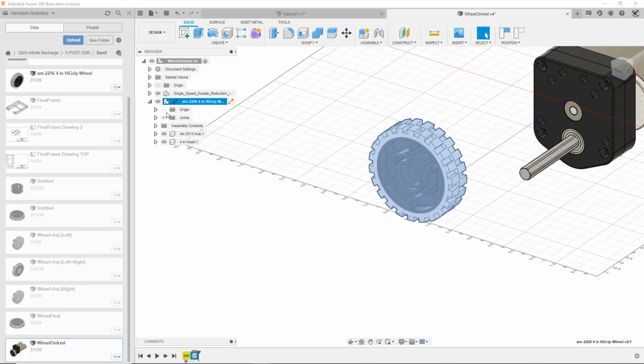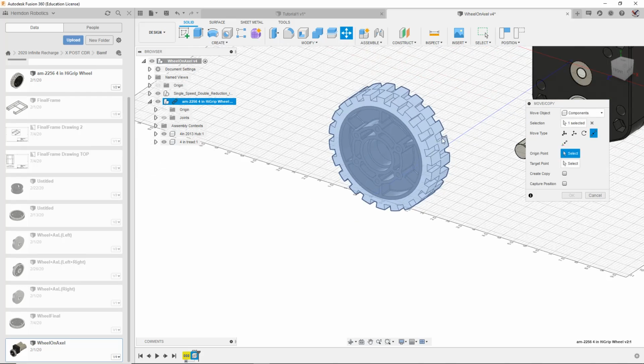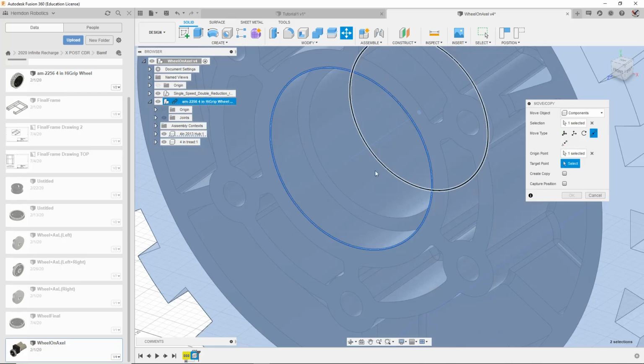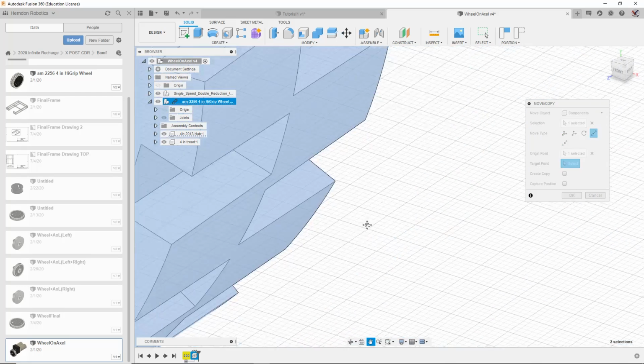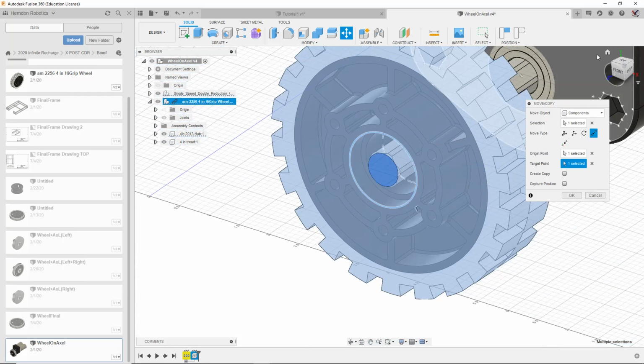So then you have these joints, all these parts, all that. What I can do is just click on this. It's like selecting a body. Hit M to move it. That's not M. Hit point to point. See, it's already facing 90 degrees up, so that's fine. Select this ring, which will automatically go off the center. Then select this, and there you go, it moved in.